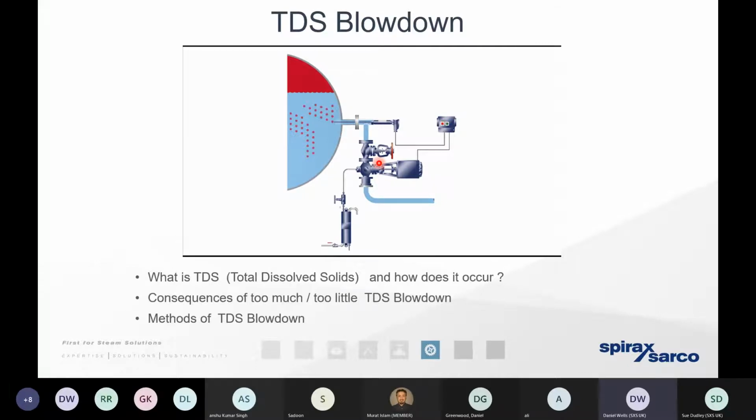But that foam is also going to dry out as scale. And that scale can be conveyed in with the steam. It can block steam traps, it can block strainers, it can create erosion of sensitive areas. It can bind itself to heat transfer surface areas, resulting in an insulating effect or a slowdown, certainly a burden of maintenance. So we want to ensure that the water chemistry is held at the correct point.